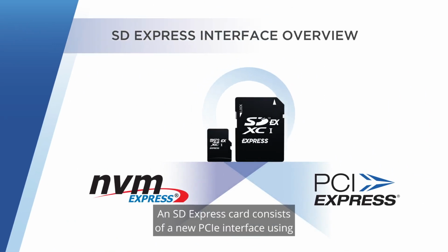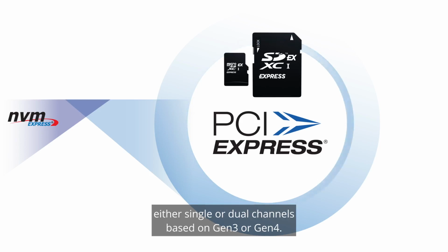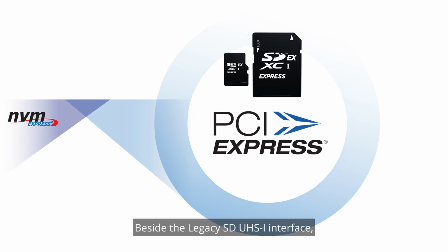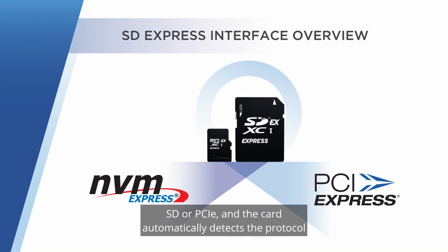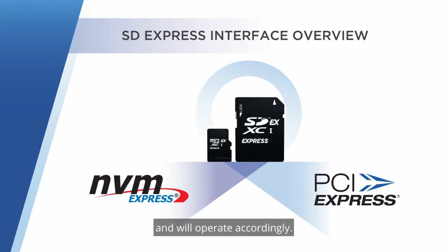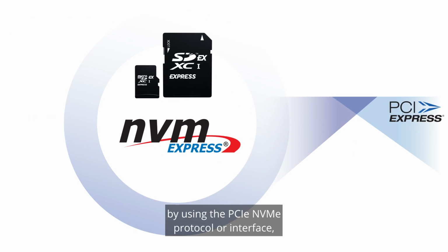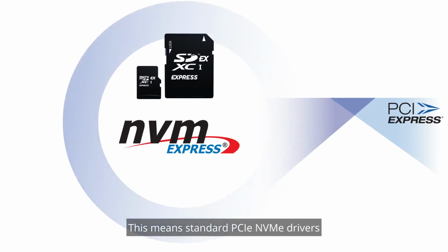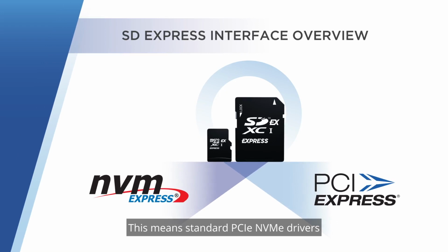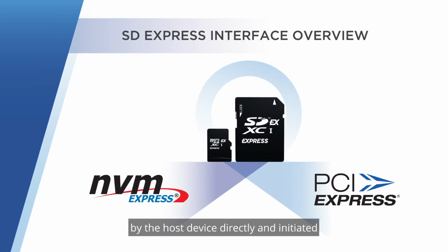An SD Express card consists of a new PCIe interface using either single or dual channels based on Gen 3 or Gen 4, beside the legacy SD UHS-1 interface. The host device may access either of the interfaces, SD or PCIe, and the card automatically detects the protocol and will operate accordingly. If the host accesses the SD Express card by using the PCIe NVMe protocol or interface, the card behaves as a standard NVMe storage device. This means standard PCIe NVMe drivers you may already be familiar with may operate the card if the PCIe interface of the card is approached by the host device directly and initiated through its PCIe interface.